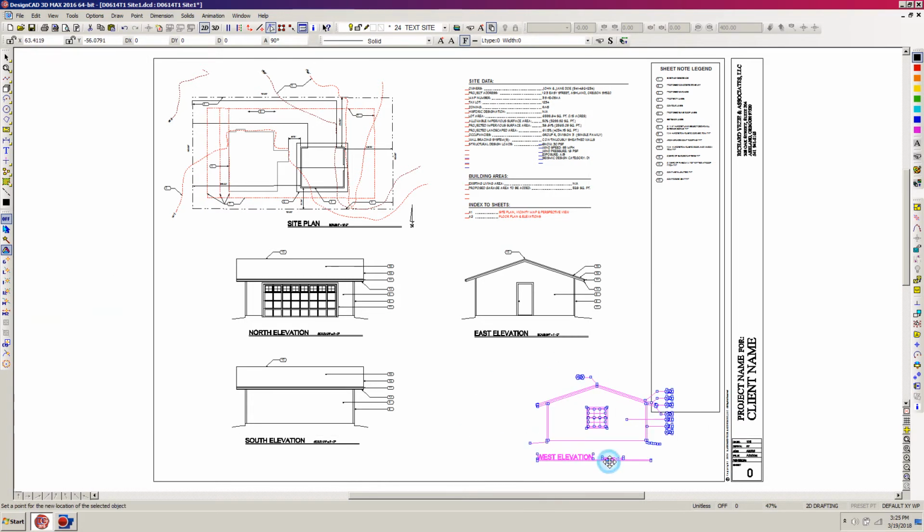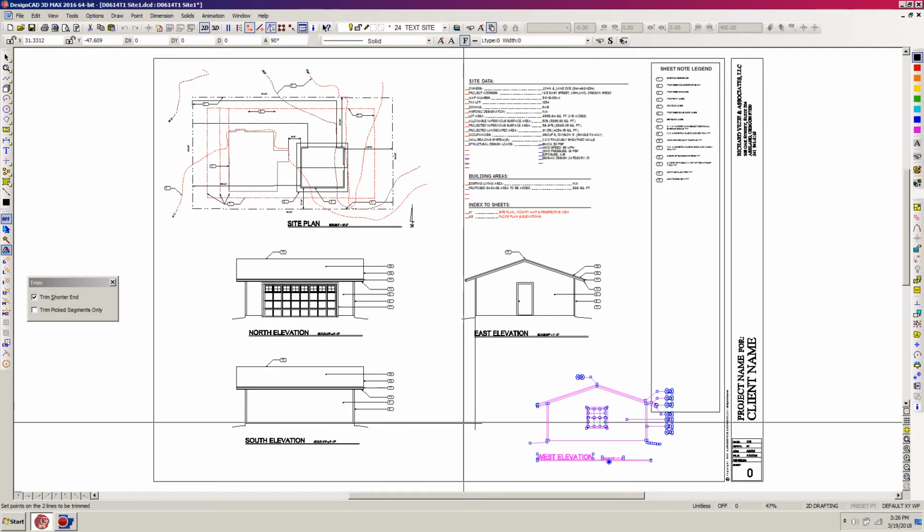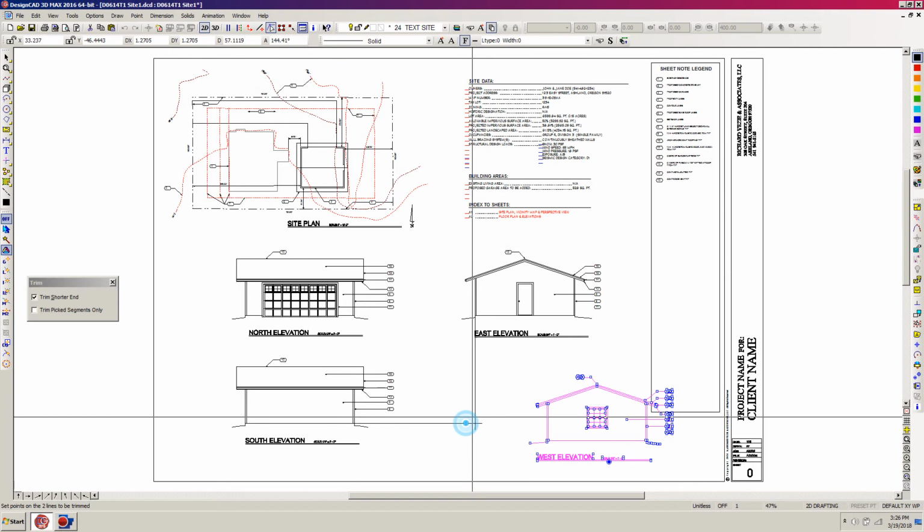So what I want to do here is I'm just going to move it out of the way a little bit down here, because the easiest way to align these 2 things is I'm going to just do intersecting lines at the corner. So I'm going to hit V for vector and just take a line from this outside edge of the wall and hit H for orthogonal mode and come on over a ways and set a point. Then I'm going to hit V for vector, and right here I'm going to right click on the outside and bring it on down and in orthogonal mode still, and then click a point and hit my scroll button to initiate. Now I'm going to hit Shift E to trim these to each other, but I'm hitting H to go out of orthogonal mode first.